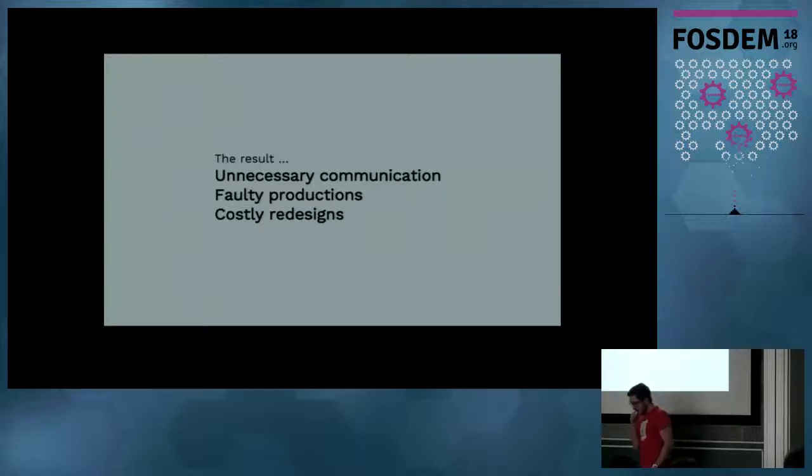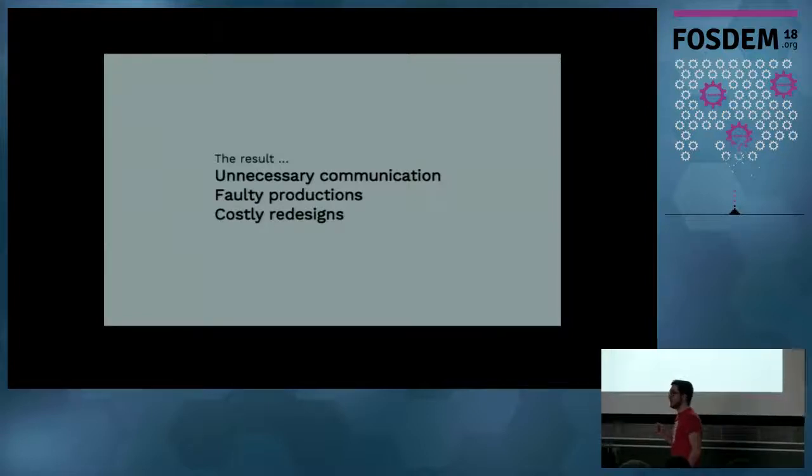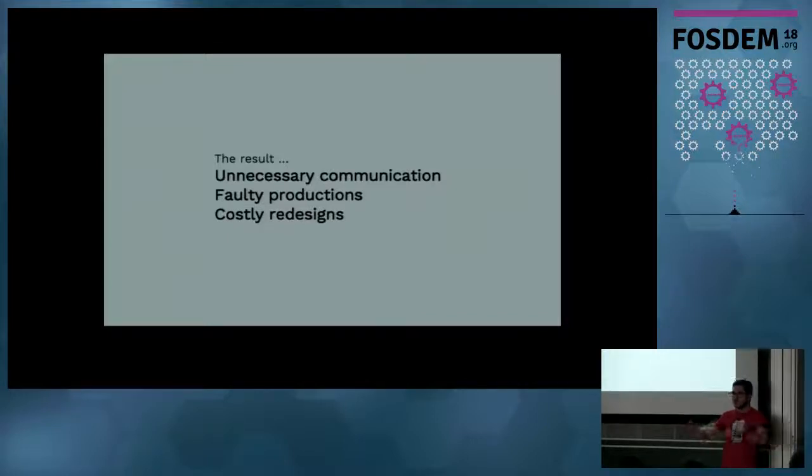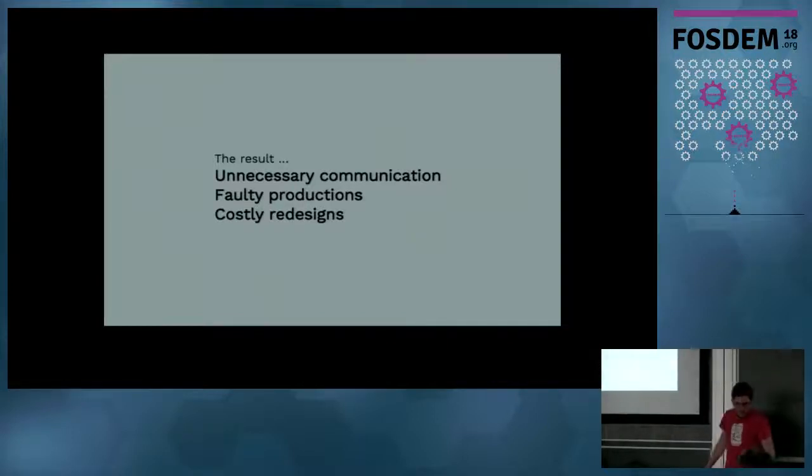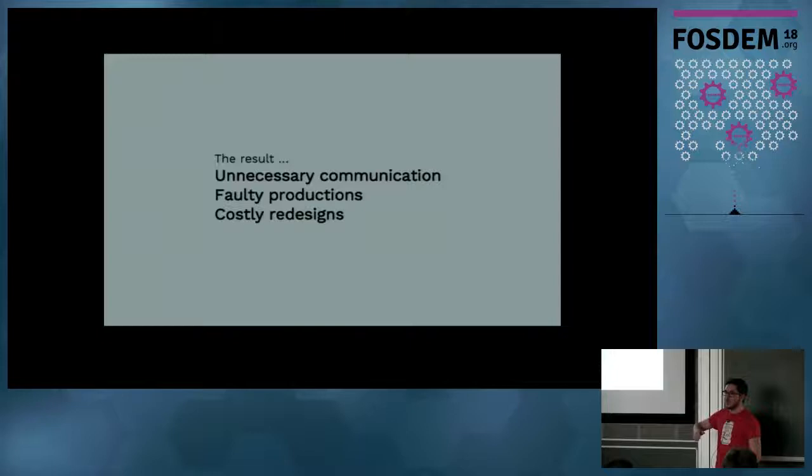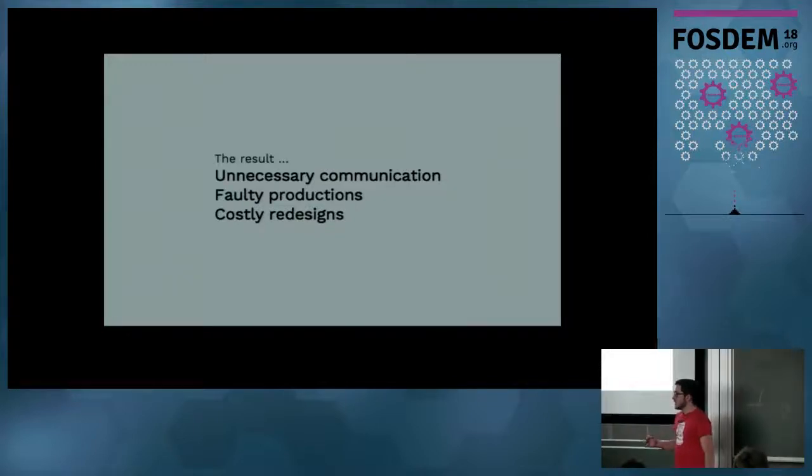Or, hey, the stencil you delivered to me actually does not fit because the shrink of the pads is not existent at all. Please shrink the pads by like 15%. This is everything which comes together later when you assemble the PCBs, which is not covered at all. And this happens when you are actually finished with your design. Because as soon as you finish, you give it off to the assembly factory, and then you notice this is wrong, this is wrong, this is wrong. I want to know that upfront, not later in the assembly.